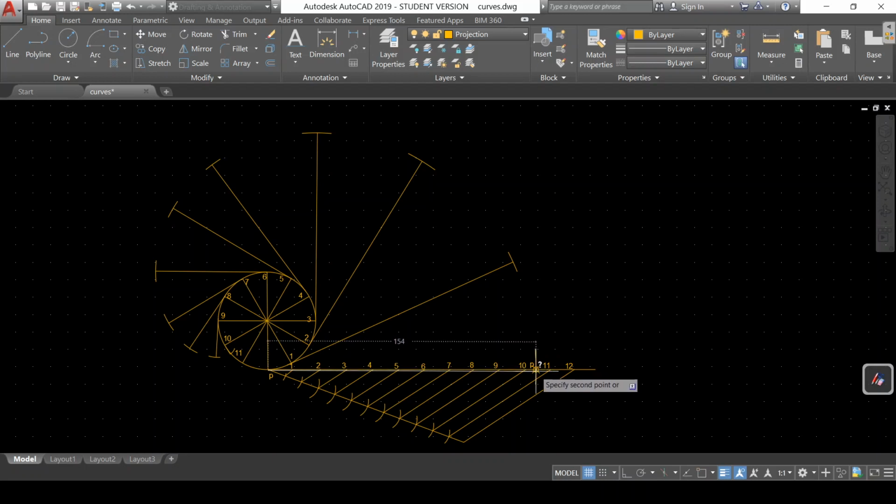So sorry, 154 mm is the given length. So we have taken that at 154 mm from the initial point. So this is our point P on the string, 154 mm away. And now we have to trace the locus of point P. So now our procedure remains the same as the previous sum here. Once we have got the P, now for the first 1/12 of this winding, one will touch here, it will be tangent here. Then we have to take the distance from 1 to P, cut on this tangent. So we'll get this point P here, and then 2 at 2 to P distance, and go on marking the arc. So this point P will move along this track, and this will be connected ultimately.